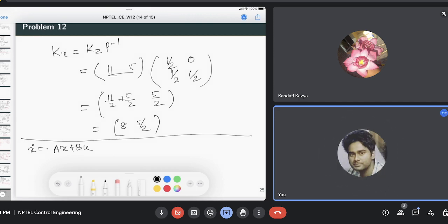For two dimensions it is easy to design in any form, but in higher dimensions it will be difficult to design in an arbitrary given form. So we transform into the controllable canonical form, which is denoted by z dot equals A tilde z plus B tilde u. We use this transformation to go from the given form to the controllable canonical form, and we design there.